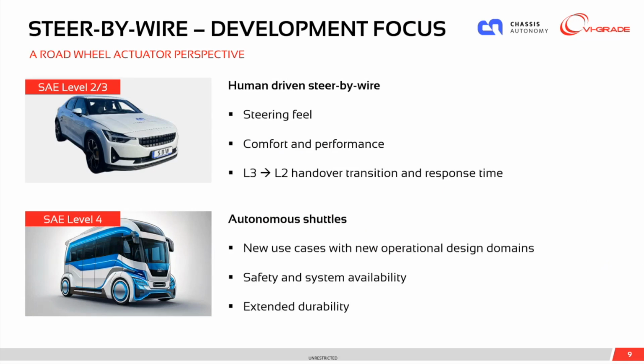Just as hydraulic power steering systems were replaced by electric power steering systems, the key requirement was to maintain steering feel. When we move from a mechanically connected system to a by-wire system, again, we're looking to now not only maintain a steering level of performance and comfort and feel, but we're actually looking to replicate what's happening at the road wheel actuator on the hand wheel to ensure the driver has comfort and also has that feeling of safety.